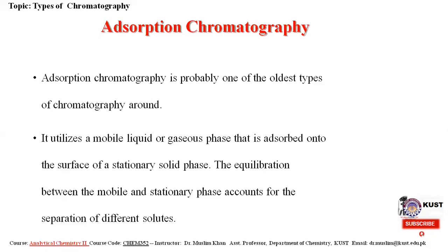This holding is due to the weak non-ionic attractive forces of van der Waals and hydrogen bonding, which only occur at specific adsorption sites or beds. These adsorbent beds can differentiate between the organic molecule adsorbates based on their strength of binding. Some molecules have more interaction with this surface; the van der Waals forces and hydrogen bonding of some molecules are greater in nature, and some are lesser. These differences in the strength of binding lead to the separation on the adsorbent surface.